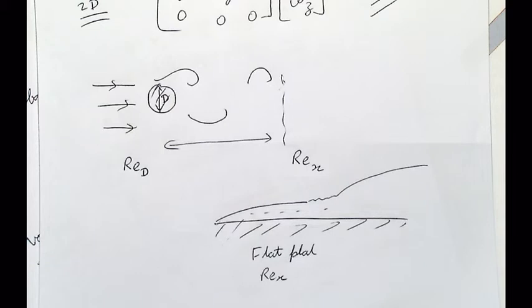But if you keep increasing the Reynolds number, let's say beyond 3,000 or 4,000, you will see that now you'll get three-dimensional structures in experiments. If you have a cylinder in an inflow, you will start getting three-dimensional structures behind the cylinder. Before 2,000, 3,000, everything will probably be planar. Does this make sense? Yes. You've done these experiments, right?